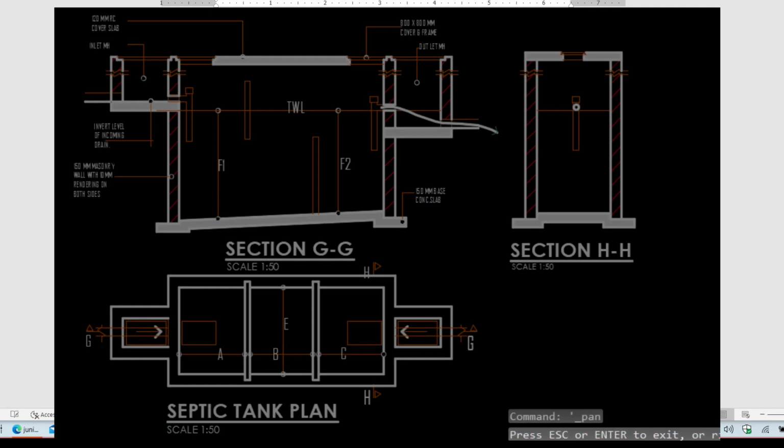Because our focus here is septic tanks, the reasons they are efficient, they are affordable, and they can be built very quickly in areas where we don't have the main sewer line, because you can channel them to a soak pit. The soak pit can drain the liquid part of wastewater after it has undergone maturation in the septic tank. So I will explore that one exhaustively here, even by use of a diagram.